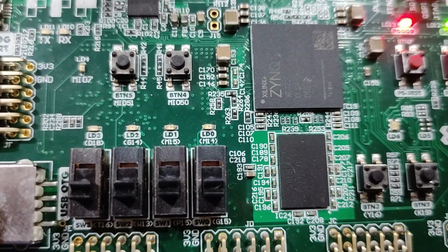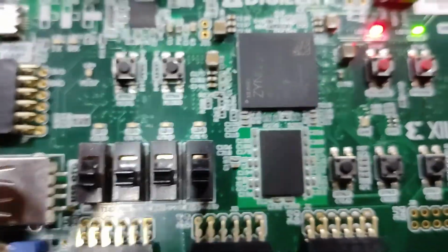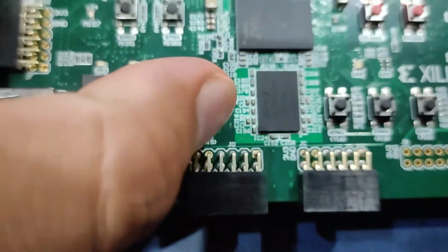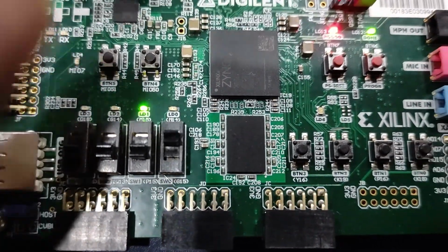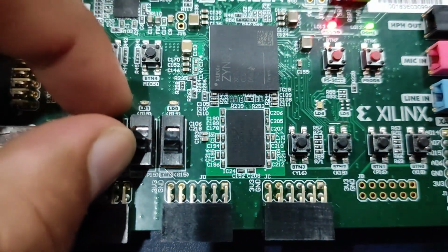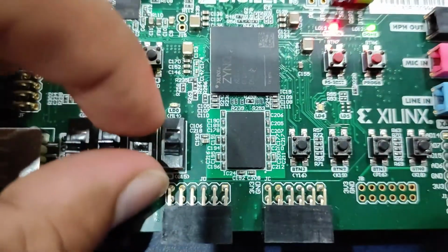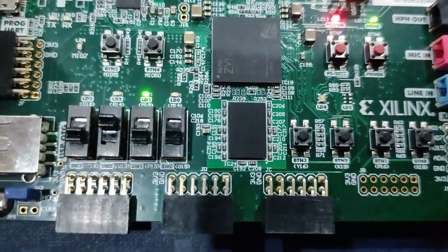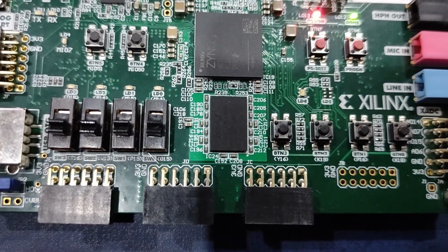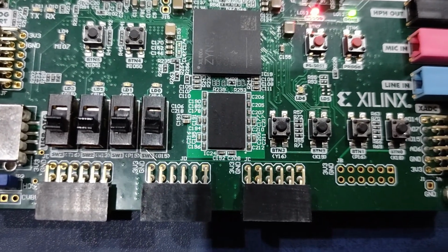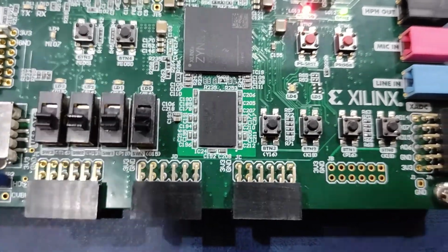When any one of the inputs becomes high, the sum LED, which is the M15 LED, becomes high. Now I am turning on one switch, and as we can see, the sum LED becomes high. Now I am turning it off again, and when B is high, the sum LED also becomes high, and when A is high, the sum LED also becomes high. This means in a full adder, when any one of the inputs is high, the sum LED is high, and when any two of the switches are high, the carry LED is high and the sum LED becomes low.